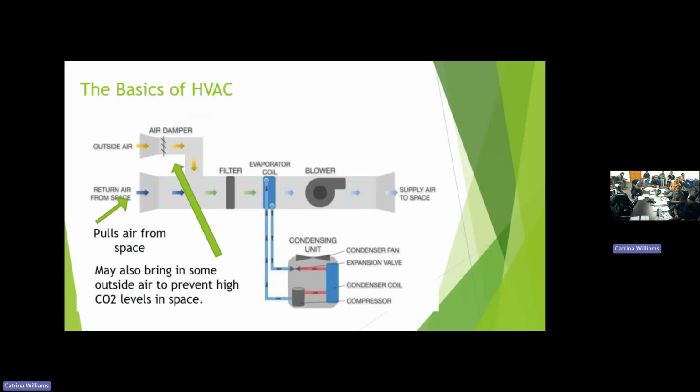So the air damper is equivalent to intake. Well, it might be more like a mixing damper, so we can control how much outside air compared to return air it is. If it's a high amount of outside air, there would probably be an intake hood on that somewhere, because we don't want rain and snow blowing into it. So there's some sort of intake hood with the damper as well. The damper might be used so we can control how much we're bringing in.